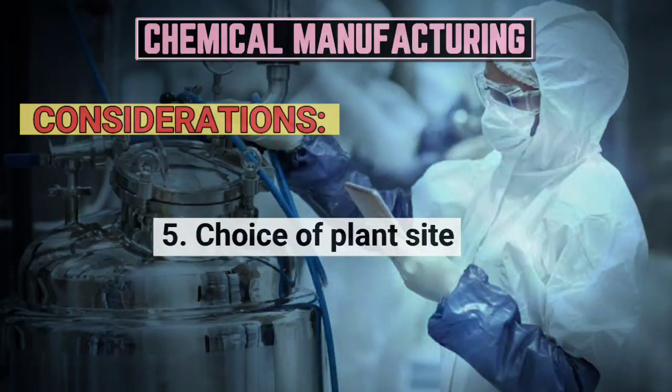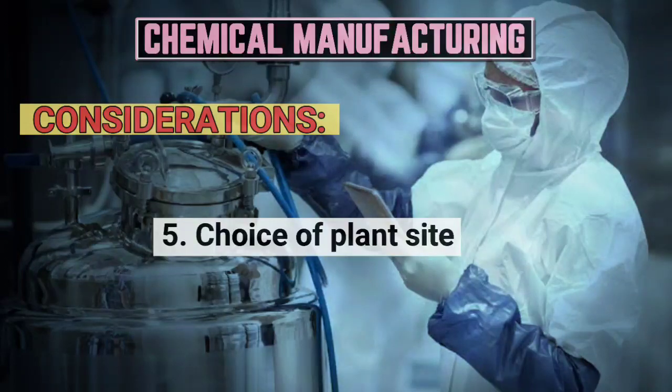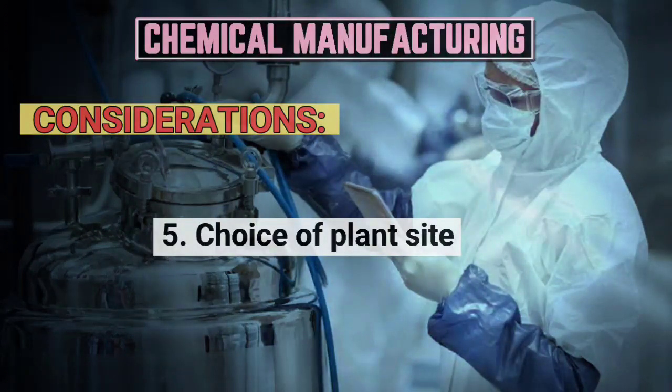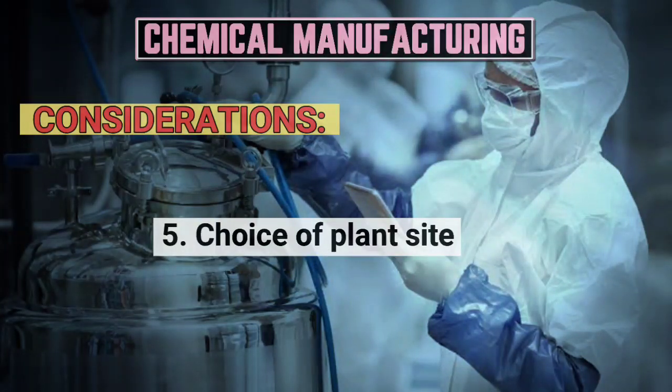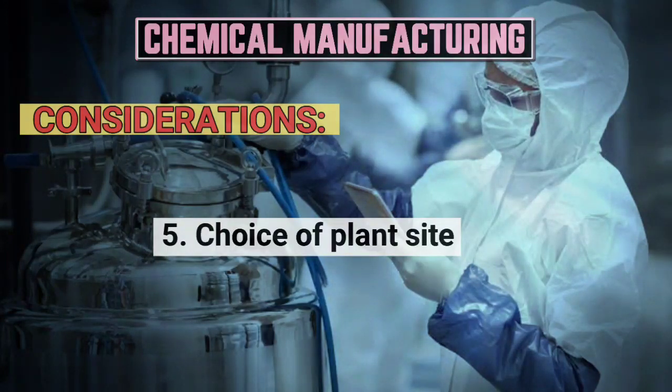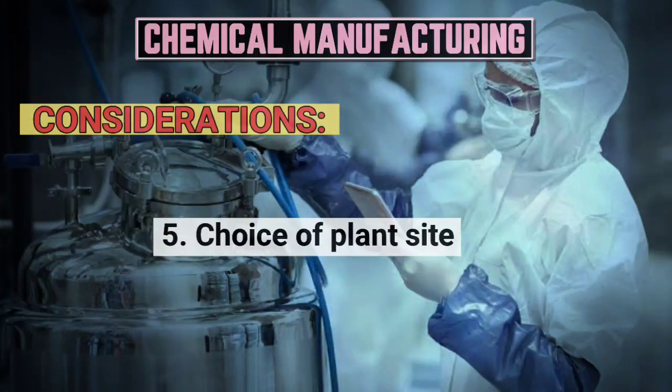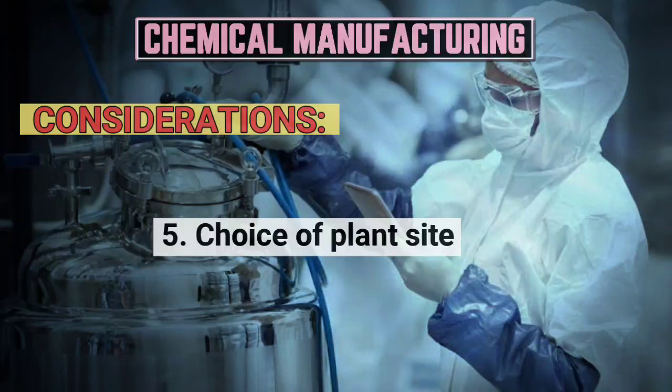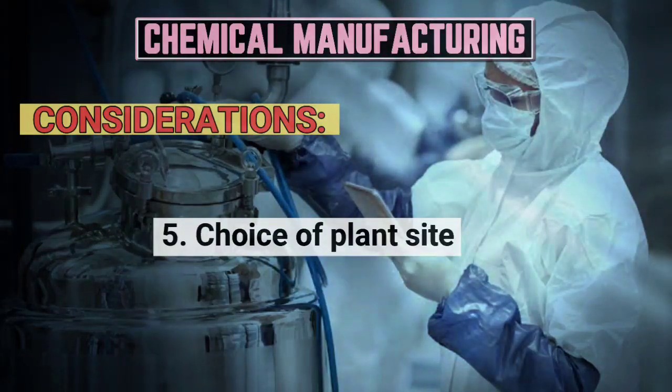So you also have to put into consideration where to site the plant. Where to site the industrial chemical plant, you have to look into the availability of raw material. You have to consider that alongside the availability of water, and the availability of electricity, which is energy. You also have to consider the attitude of the authorities towards disposal of effluent, and look at the availability of local labor force to provide faster social services to the community at large. So the site has to be properly situated.